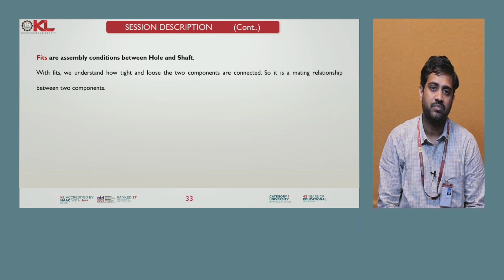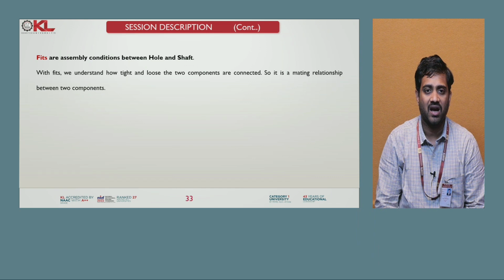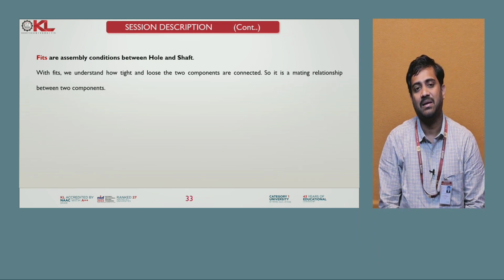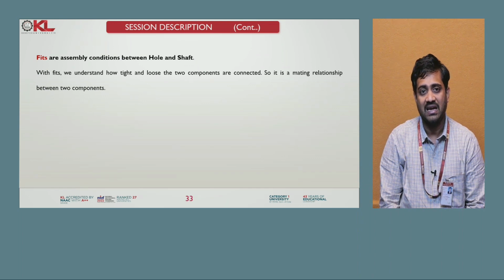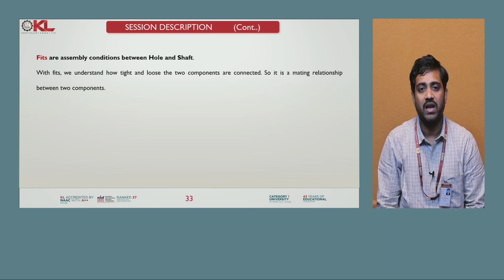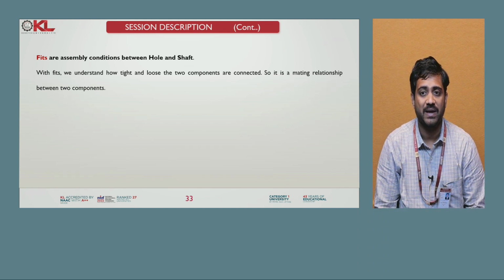At the same time, whenever there is more clearance between the hole and shaft, the shaft is going to vibrate, so wear and tear problems will come into the picture.